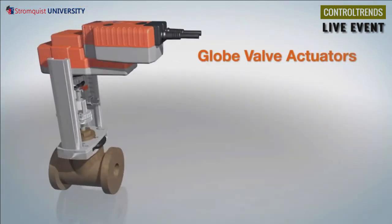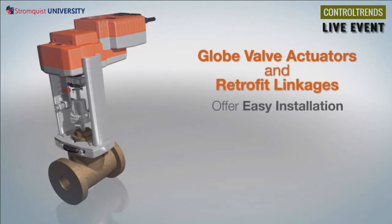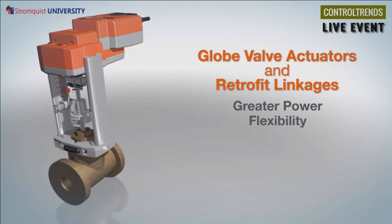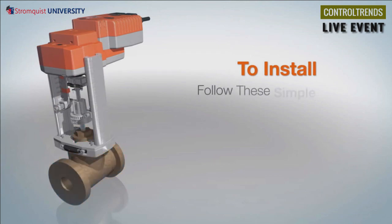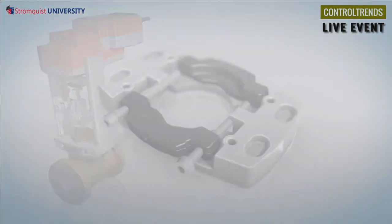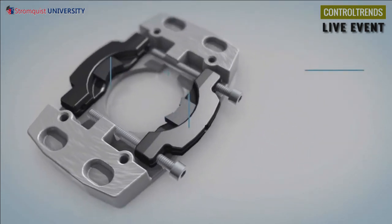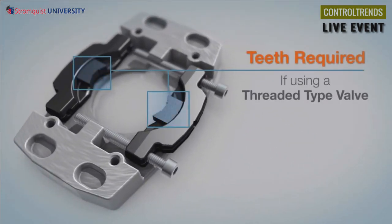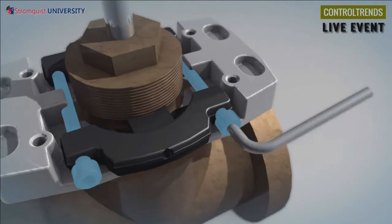Belimo globe valve actuators and retrofit linkages offer easy installation with greater power and flexibility. To install the valve actuator and retrofit linkages on globe valves, follow these simple steps. Define valve bonnet type and install teeth if needed. Teeth are required if using a threaded type valve. Place the clamp over the top of the valve. Tighten evenly using the 2 screws provided.